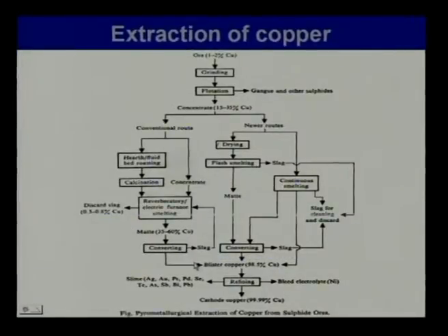Let us start with copper. Now, I mentioned that there is a beneficiation technique called flotation, which makes it possible to concentrate low grade copper ores to produce a concentrate that will have much higher concentrations of copper.